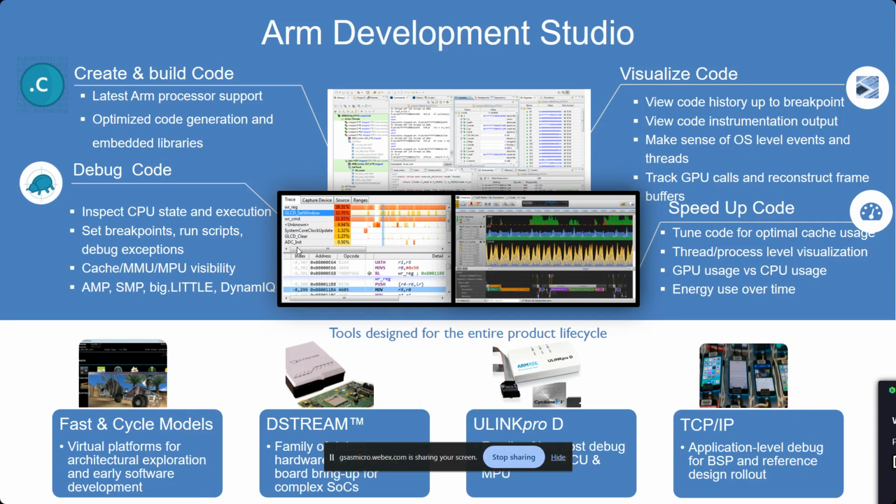In such a big little combination, they can optimize the system, where at power on reset the small core, in the example Cortex M4, starts executing while Cortex A5 stays in standby. The M4 does all the required system initializations and then releases the Cortex A5. Then Cortex A5 takes care of all higher end processing, while lower end processing is still done by the Cortex M4. Thereby the CPU is utilized to its maximum extent based on the application requirement. This technology was brought by ARM very long back.